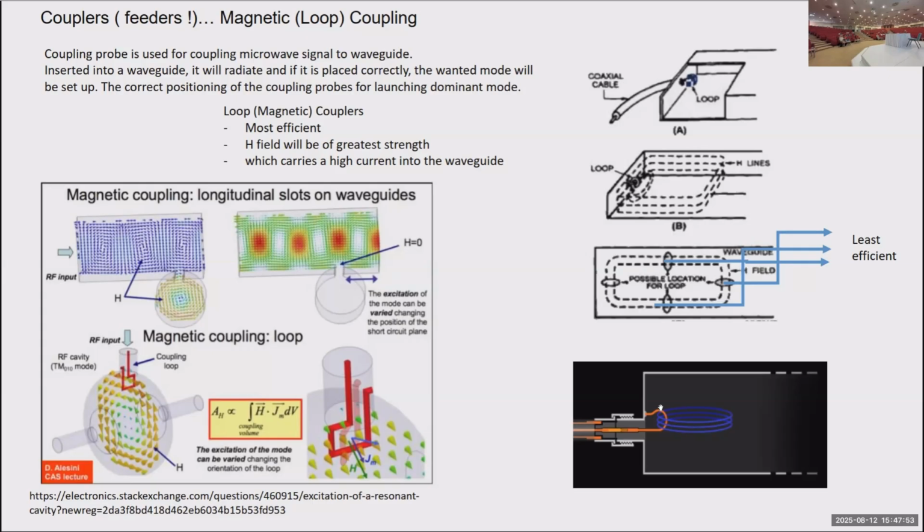Hocam, may I ask you something? Yes. In that magnetic coupling, why is the antenna just one loop? Why not more than one loop? You can do another, but then the inductance will change, because I talked about the Qs. The input impedance should be Z0, and we solved the ZI. The impedance is very different. So we need matching, impedance matching, because ZI will be different.